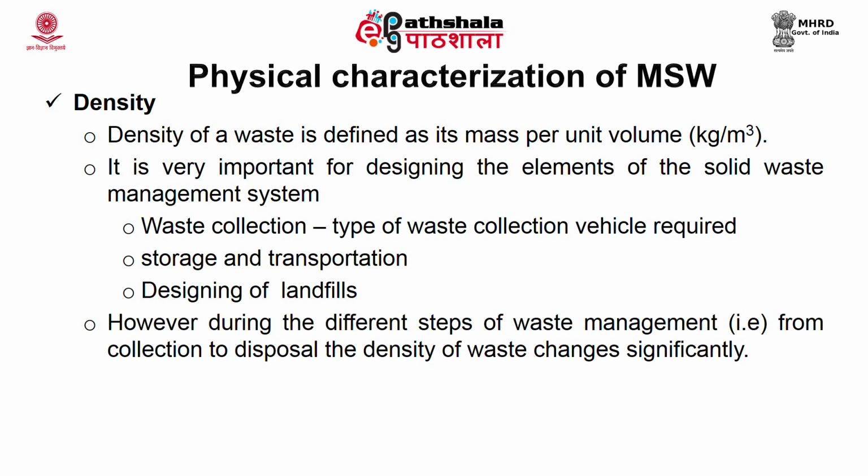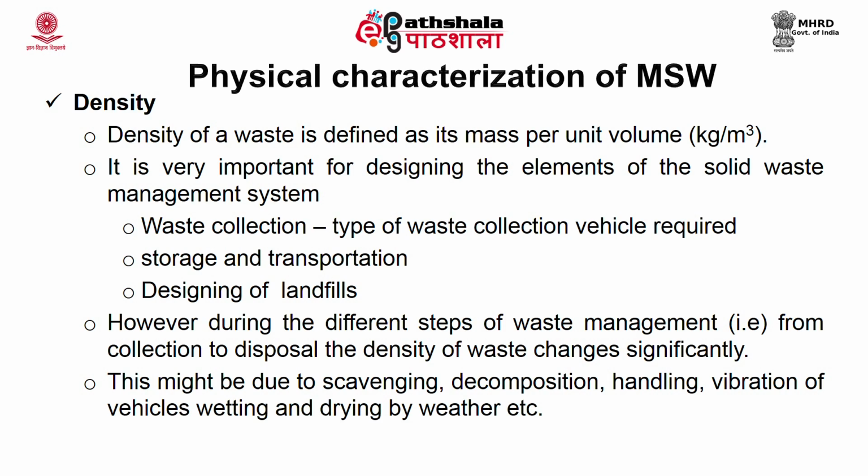Now, the density of waste is affected during the waste management system, that is beginning from your collection to the waste disposal. The density of waste keeps changing significantly. The reason might be due to the decomposition, scavenging, handling, vibration of vehicles, wetting and drying, and other weather phenomena can also influence the density of waste. So, that is why the density of waste varies significantly from waste collection till disposal.